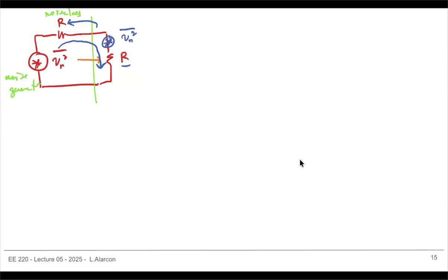But again, you sort of say, but we can measure noise, right? So this is just another thing. We just said that if I connect the noise to an oscilloscope, since what we're getting is a mean square, if I take the square root of Vn squared, that's actually your root mean square, right? There's a non-zero RMS that I can measure.